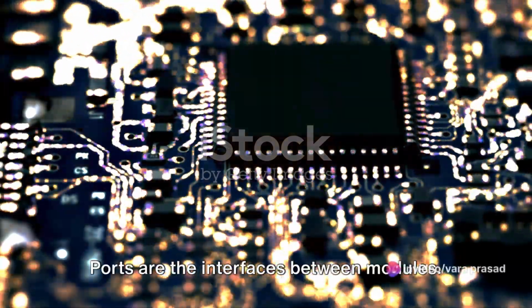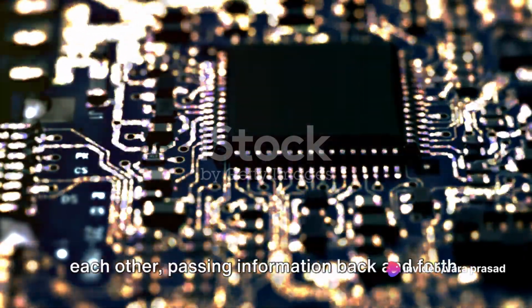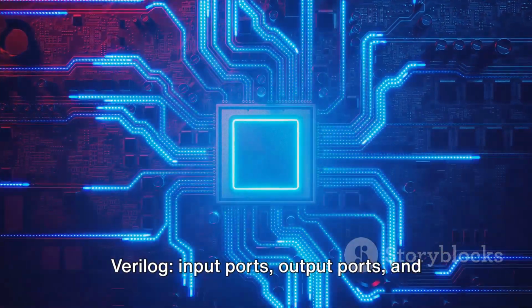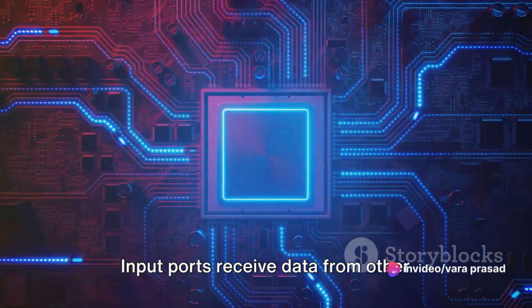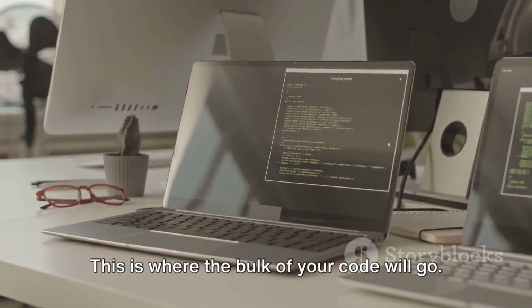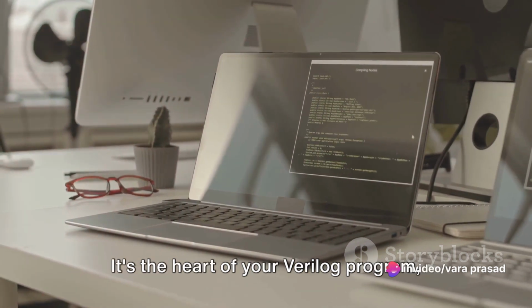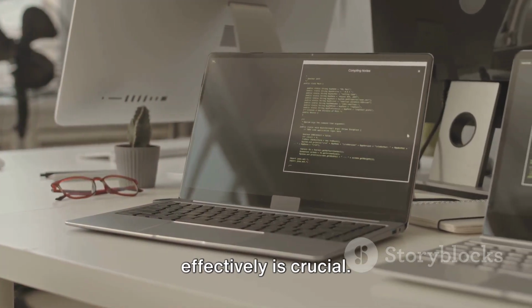Next up, we have ports. Ports are the interfaces between modules. They allow modules to communicate with each other, passing information back and forth. There are three types of ports in Verilog: input ports, output ports, and in-out ports. Input ports receive data from other modules. Output ports send data to other modules, and in-out ports can do both. Lastly, the main body. This is where the bulk of your code will go. It's where you'll define what your module does and how it interacts with other modules. It's the heart of your Verilog program, and understanding how to structure it effectively is crucial.